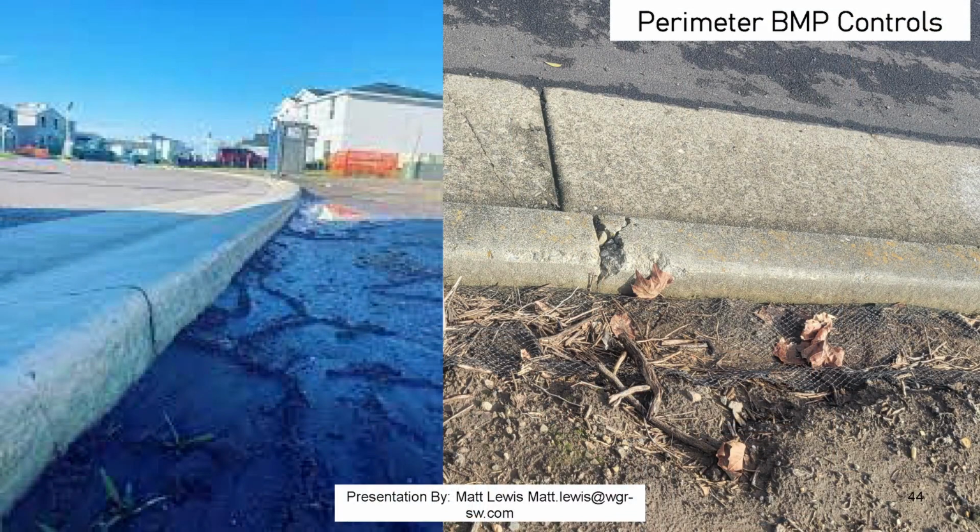Now this is interesting, curb cutbacks. A 6-inch curb cutback is a state-approved BMP. It is a perimeter control. This is a cost saver like you would not believe. If you have curbs, even if you're trying to remove your curbs eventually, leave them in for as long as possible, because what's better: to have a pre-existing curb that's already there, or spending money to put fiber roll down? So a 6-inch curb cutback is a fantastic BMP, and it replaces the standard fiber roll.